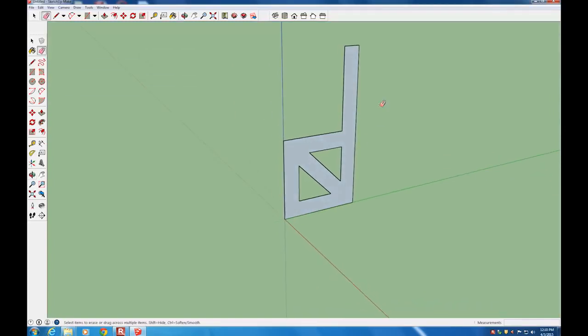And so now I'm going to rotate just a little bit so we can get a better view of the extrude when we do that, and then go over and select, from the Large Tool Set, the Push-Pull tool, and then hover over the whole face of the chair. It'll highlight blue, and then click and drag the direction we want to go. And we only want to make this 0.02 meters thick. So I type in 0.02 and then Enter. And so now our chair has thickness.